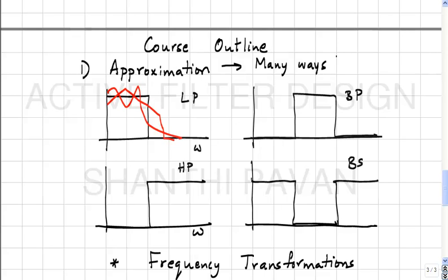which therefore means that there are many approximations in practice. In other words, there are many ways of deriving a ratio of polynomials which will approximate the ideal brick wall in some sense, optimal to the originator of that approximation. I will discuss some popular, commonly used approximations. I am sure many of you have heard of what are called Butterworth